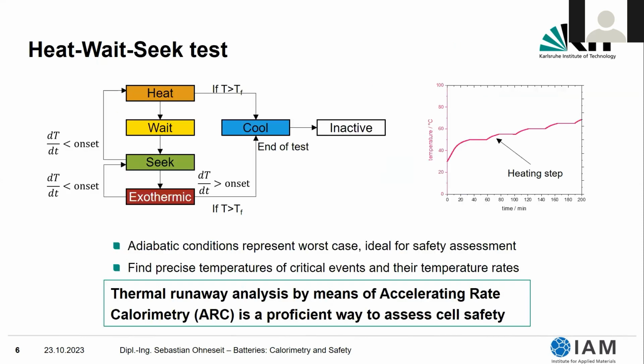Talking about the test, this is a schematic view of how the test that I will be presenting, which is also the standard thermal safety test, is going. It starts with a defined heating step. Most of the cases it's 5 degrees C. You can also see here the different heating steps.